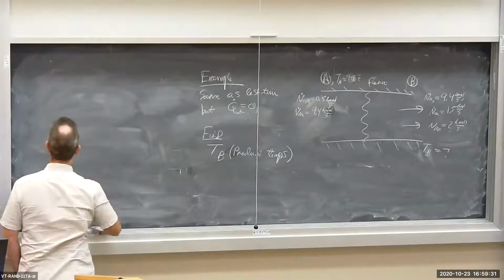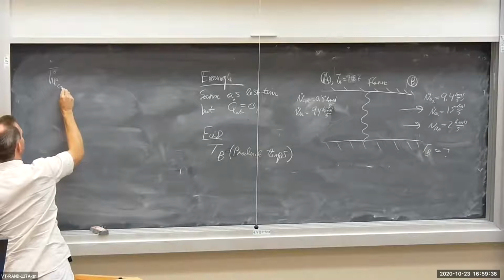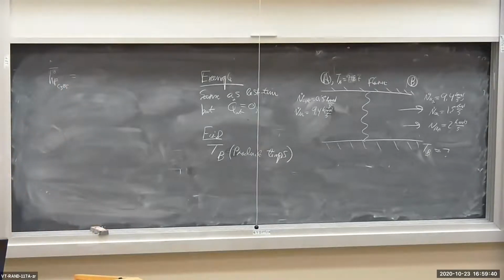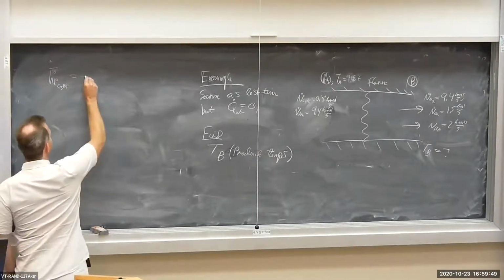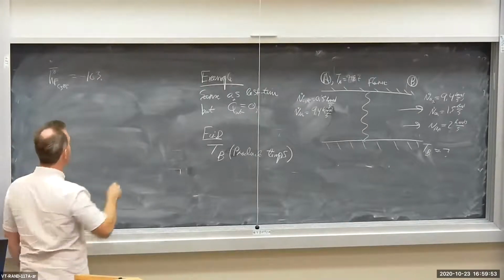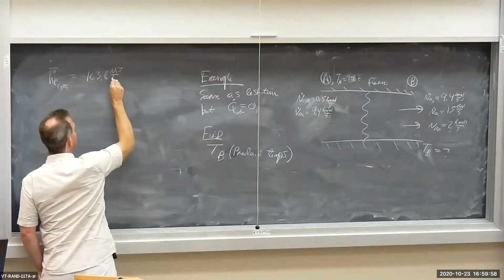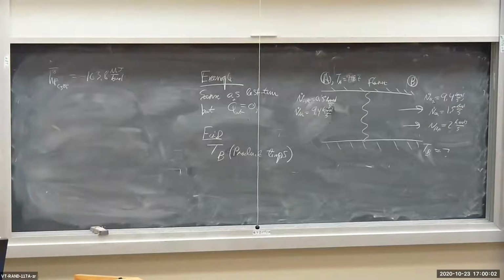Let's make sure we write those down. So enthalpy of formation for the propane. That's from a table. We already looked that up before doing the previous problem, but let's write it up one more time. The enthalpy of formation for the fuel is negative 103.8, and that's going to be megajoules per kilomole. Let's show you again where that comes from.